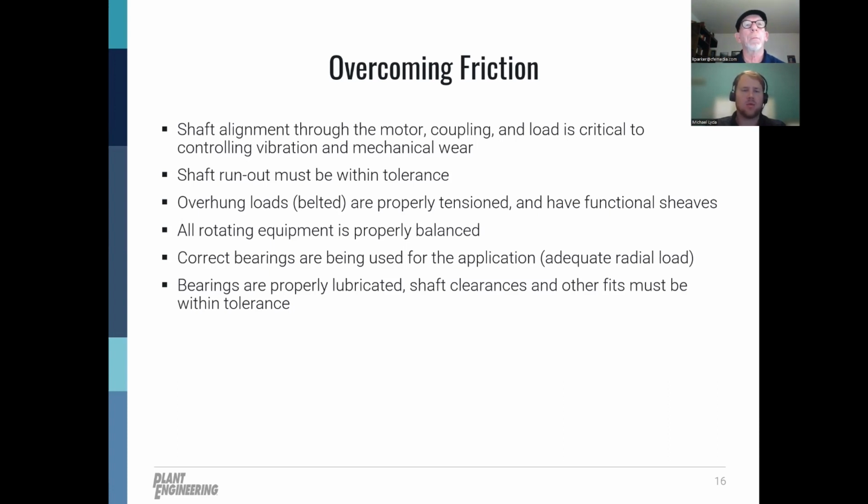One thing to pay attention to, we don't have the slide here, we've had it in the past: the bearings are the number one cause of failure for your motor. So it's very important to follow your preventative maintenance routines with the bearings. And what are those? Periodic lubrication and vibration analysis. We'll get into the vibration analysis a little bit later on. It's a little more complicated.